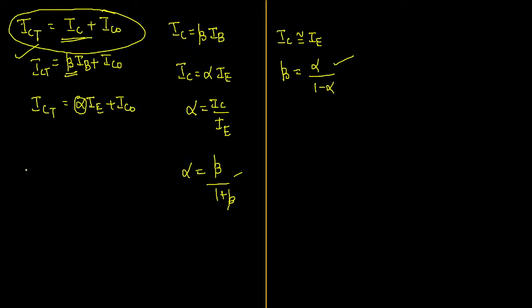Okay sir. In the same way, in terms of completely alpha, how should I write the total collector current? And in terms of complete beta, how should I write the collector current, sir? So first I am writing the total collector current in terms of alpha. They will be giving you all the data in your examination, just to follow it up. Okay, so this can be written as alpha times of IB divided by, just now I have written this relation, plus saturation current.